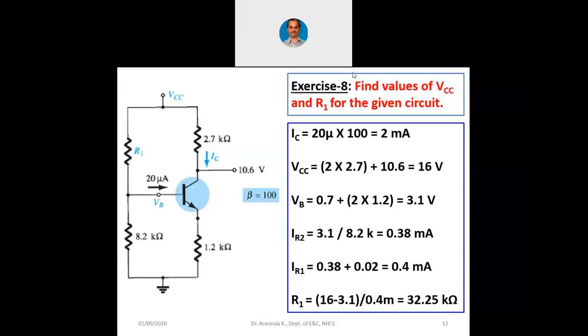So to summarize, we have been discussing common emitter configuration. And in the common emitter configuration, output current is larger than the input current and the output voltage is 180 degrees out of phase with the input voltage. These are the 2 points, and there are many other subtle points. All these other subtle points such as impedance and gain we will discuss later on in this module itself when we perform AC analysis. Till now on the circuitry we have been doing only DC analysis. Later on we are going to perform AC analysis as well.